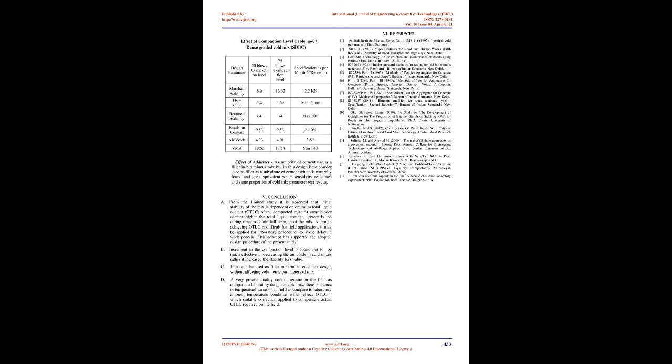V. Conclusion. A. From the limited study it is observed that the initial stability of the mix is dependent on the optimum total liquid content, OTLC, of the compacted mix. At the same binder content, the higher the total liquid content, the greater the curing time to obtain full strength of the mix. Although achieving OTLC is difficult for field application, it may be applied for laboratory procedures to avoid delay in the work process. This concept has supported the adopted design procedure of the present study.